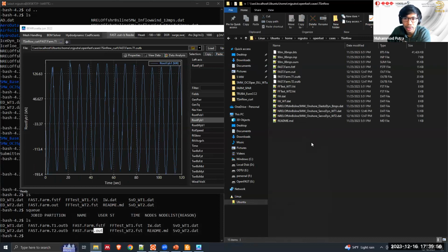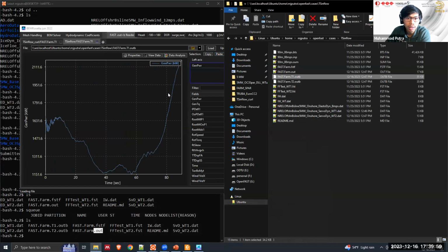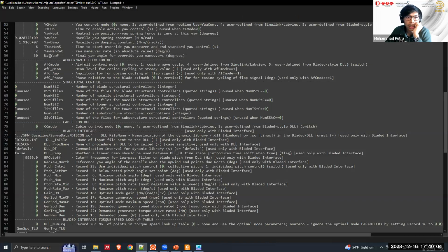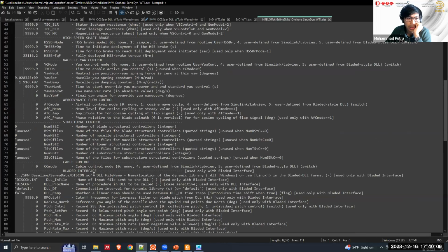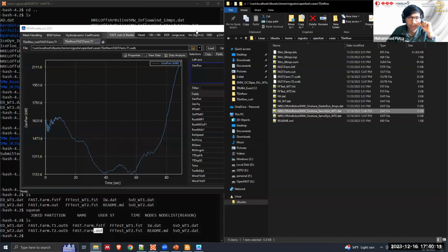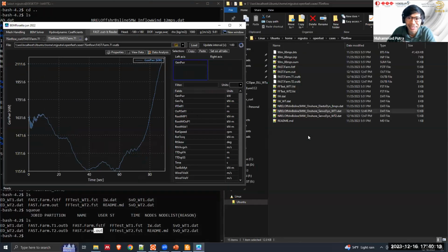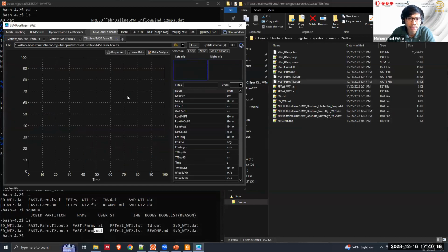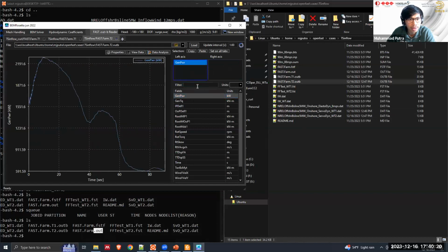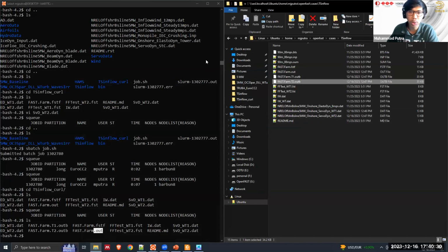Let's see from the other whether we have, okay. See, for this one, the one we have changed to 5 and then the correct controller, we have power output. So don't forget to change that because it's very important. Okay, this is from one of the turbines. We can change actually to model the other turbine. So as you can see, after some point, the wake hits and then the power drops. So it's actually better to simulate all of it together.